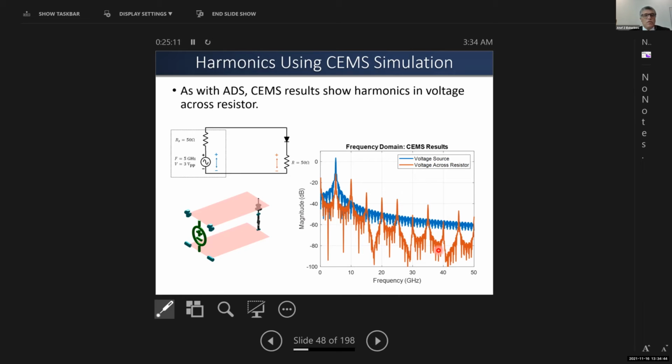That's the main difference between solving a problem in frequency domain, like when you use finite element, for example, in HFSS or some other solver where they rely on integral equation and frequency domain solution. You have to do the solution at every frequency if you would like to get a solution at a wide band. In a finite difference time domain, you do the solution only once, and you should be able to get multiple frequency solutions.